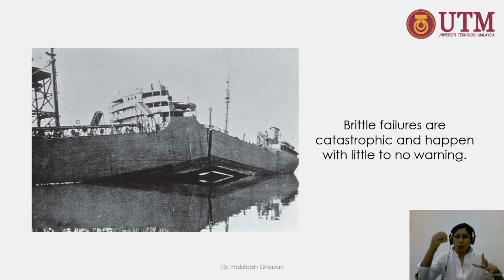inspect it. When the material behaves in a ductile manner, you can see that it starts to deform. But with a brittle manner, you cannot see it. It is just going to happen instantaneously. With a ductile manner, you will start to see some yielding or deformation. But with brittle failure, it is a rapid fracture. So designers have to be very aware if the material that they are going to use in their design is going to behave in a brittle or in a ductile manner.